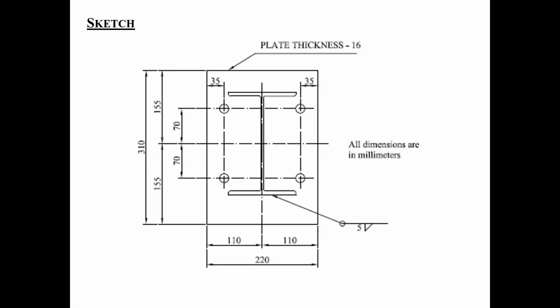It's just like in reinforced concrete. You don't show the d, you show the h, you show the cover. These are dimensions that are totally irrelevant for the guy that wants to build your structure. Where do you see any N here? The 35 is called the edge distance, from the edge of the plate to the center of the hole. That you want to specify, you understand?